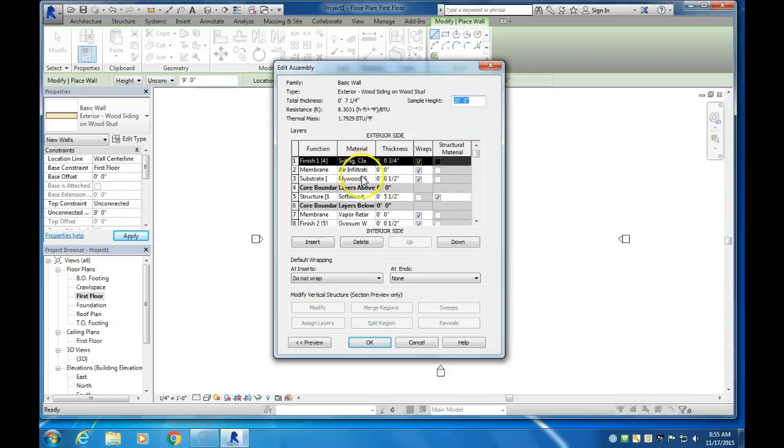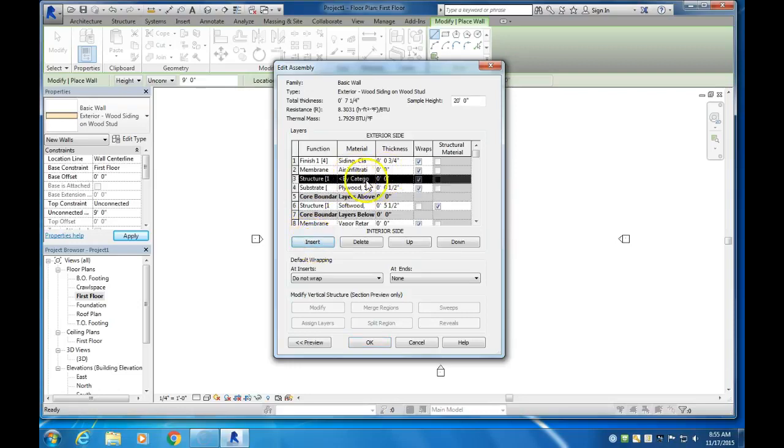You are going to have to insert a layer. If you look at your Habitat for Humanity guidelines, I believe it says something like some type of styrofoam insulation of some thickness needs to go on the outside of the plywood, but on the inside of the siding. So make sure that you do that. I'm going to delete that right now because I want you to look at that document and make sure you do that on your own.